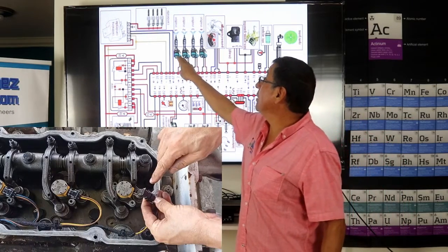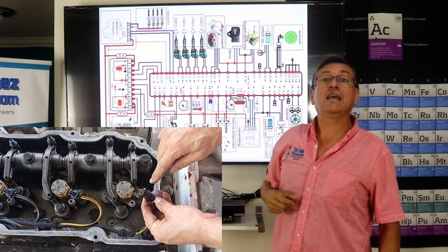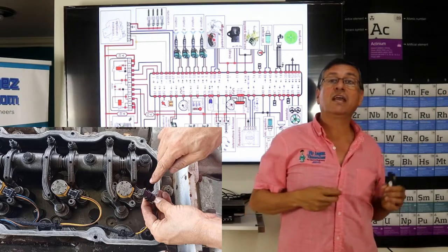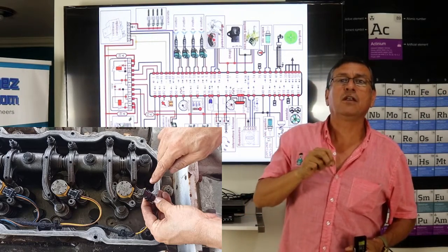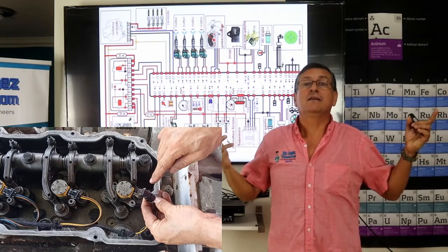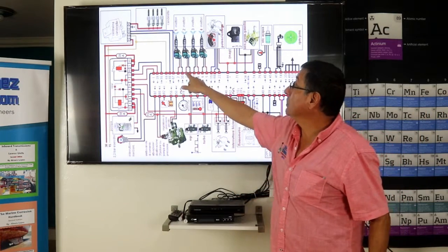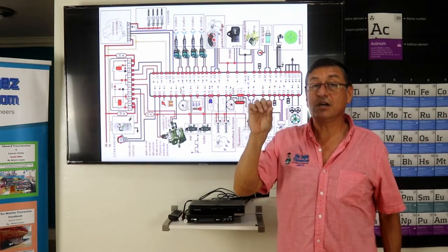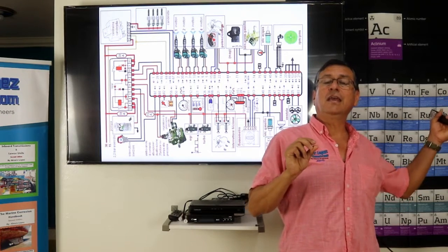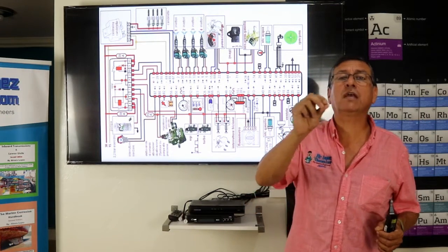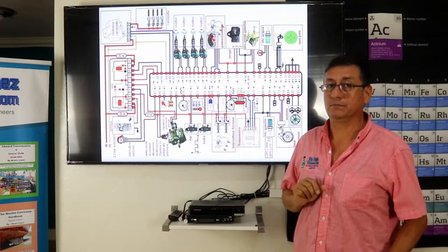Let me check on top of the injector. On top of the injector, if I have 4.5... No, I don't have anything. Okay, the cable is interrupted between the socket of the computer and the injector. I need to follow the cable or replace that cable.